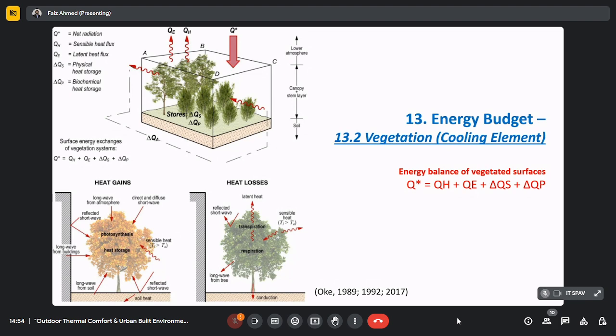And in ENVI-met, as I was telling in other sessions as well, we always model buildings, walls, roofs, windows, and so on. We can model trees in ENVI-met. That's the advantage. If you have documented real trees and want to replicate them as realistically as possible, there's a possibility of recreating the trees in the ENVI-met model and then importing them into the simulations to check.